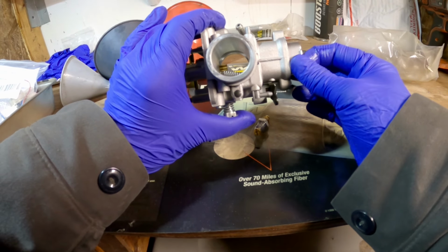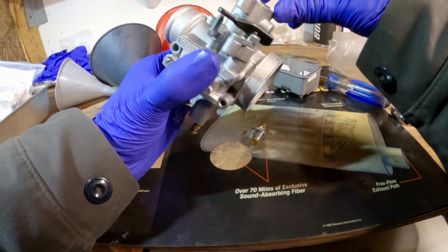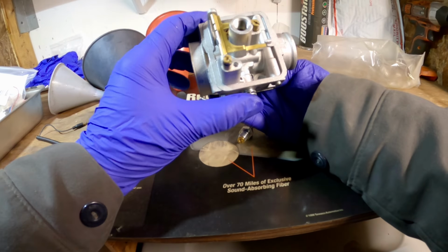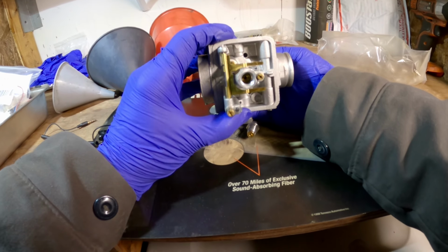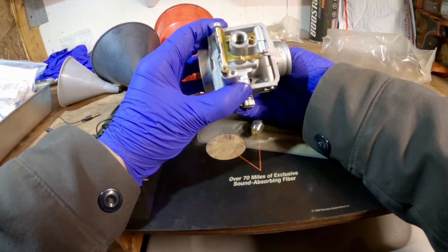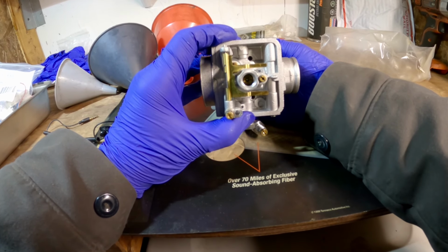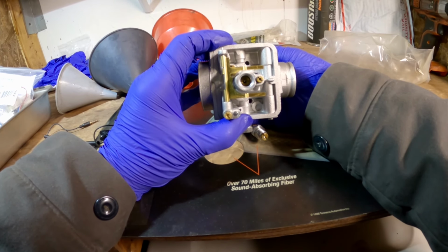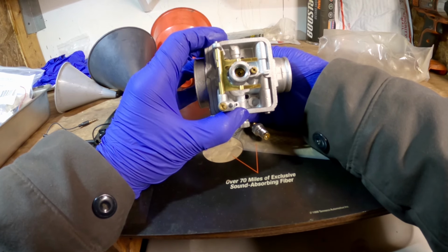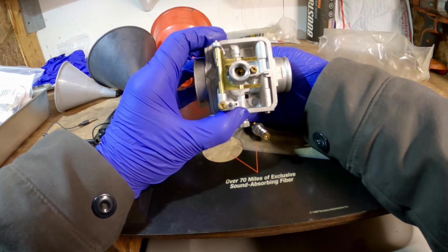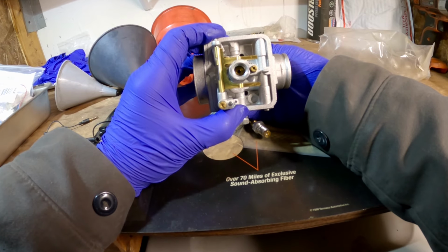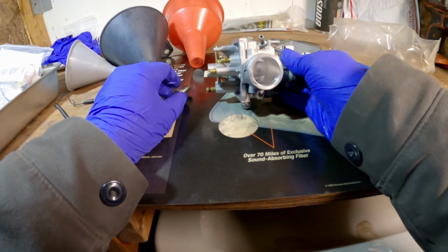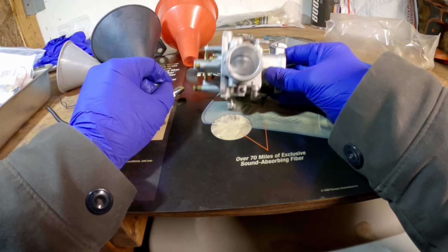So when the throttle is put in correctly, look at that. You can even see the needle through there. See that? So as it comes open, it opens up the orifice. As we close it down, it creates a restriction. So as you open the throttle more, you get more fuel flow. Because as you open the throttle, there's more airflow, so you need a proportional amount of fuel to be added as you open that.